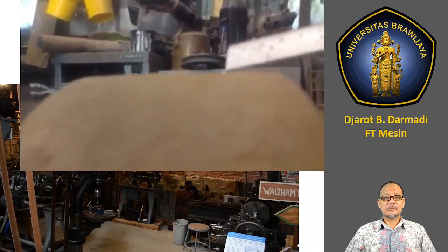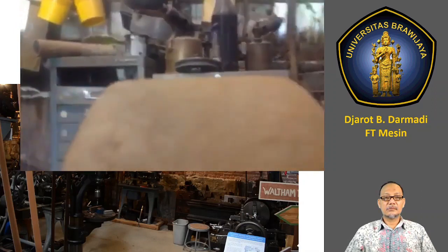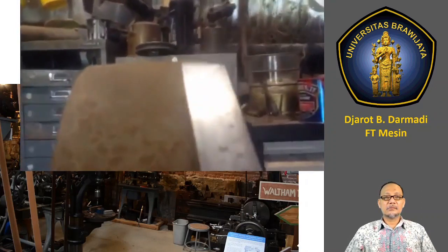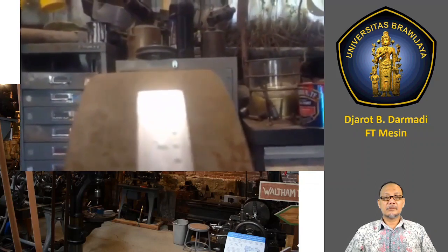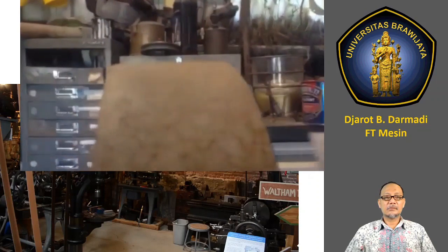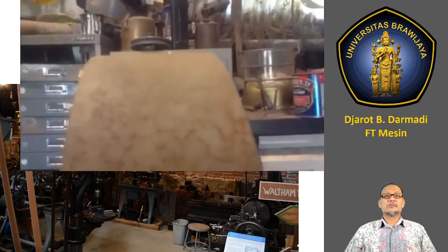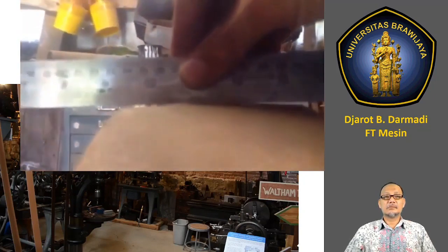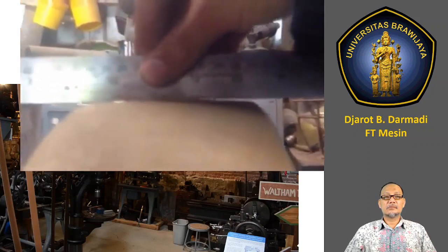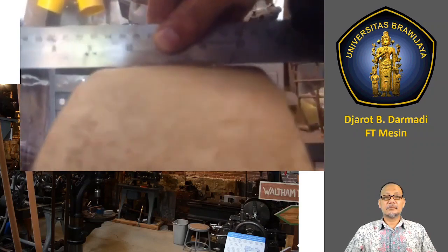So what's happening is the belt actually moves up. So the top is higher than both ends. And what that means is, when the belt is put on, the belt will always want to run to centre. That's why sometimes you see the belt sort of rocking backwards and forwards. What it is, it's because it's curved going up. That keeps the belt in the centre. So next time you go to a rally and somebody says, how does that belt stay on? Either direct them to this video or you can feel really smug.